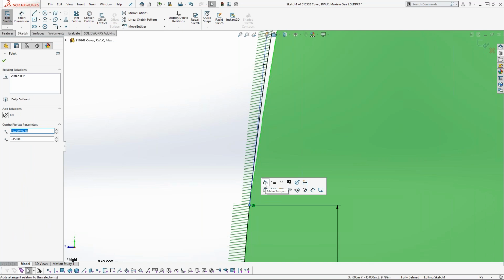We can see those curvature cones update. Or I can go to make equal curvature, but we can still see that there's a break there in the middle. In 2020, we now add in G3 torsion continuity in order to really smooth out this transition between the two.